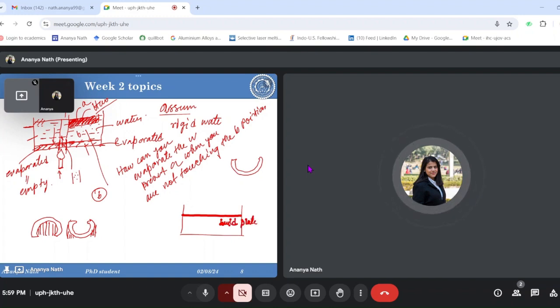Now over my build plate, the powders are spread using a recoater. And now the laser is coming and melting the powders present over the bed, and the powders are then getting solidified. That melted portion is getting solidified. And now in this manner, when you are trying to deposit this part, when you want to print this portion which is overhang, you have to have something below this that can act as a support structure from that portion to the build platform.